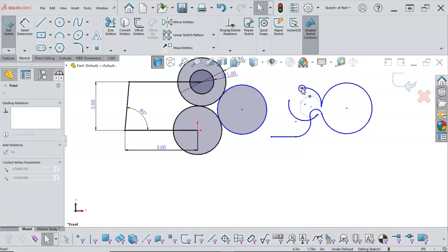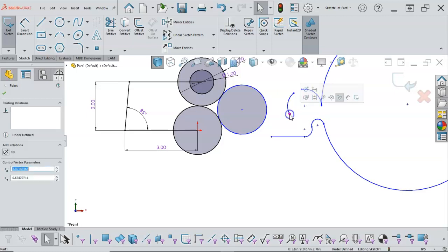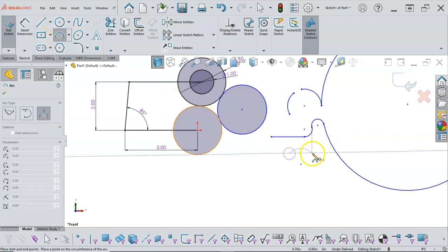And they do not have to be connected. And so it will shift and do whatever it's going to do. And we can move it closer to position and build other geometry around it on the co-radial. So the 3-point arc, then pick the start point, the end point, get it to an approximate location.